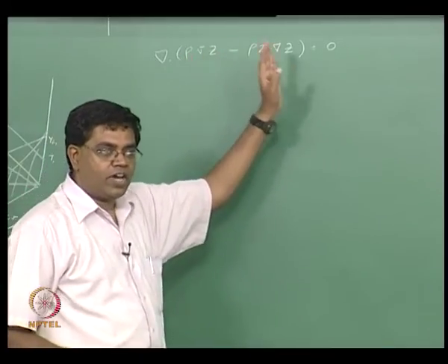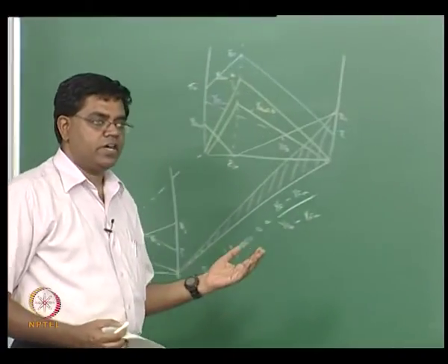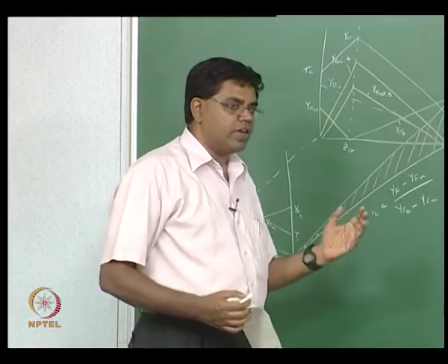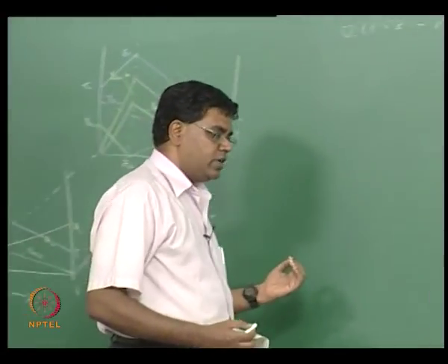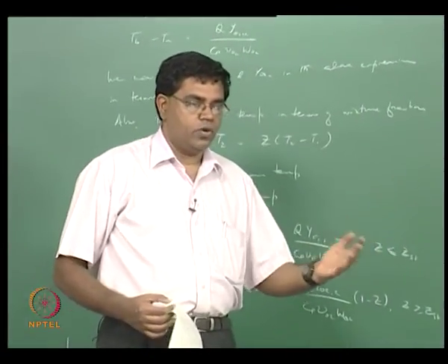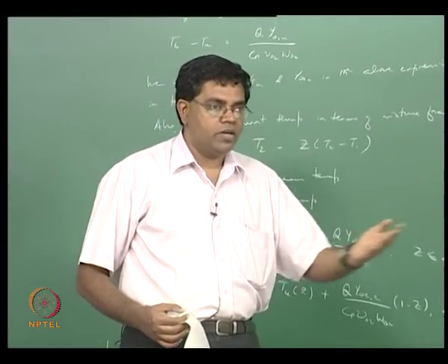You can actually derive this mathematically in two different ways. One, go back to the definition of mixture fraction. Mixture fraction is nothing but a fuel mass fraction kind of notion. So you can now find that you have something like nu YF minus YO2 divided by something, or plus nu YO2 divided by something.